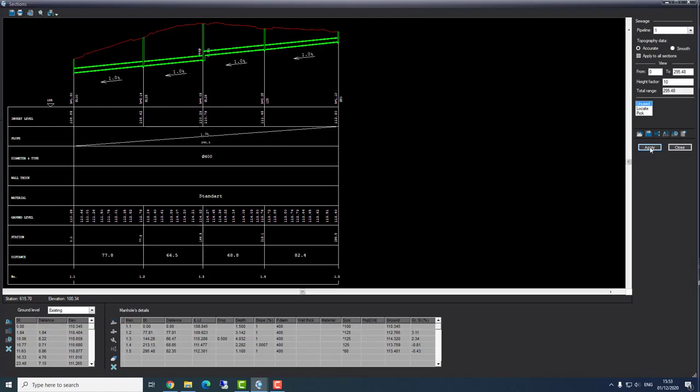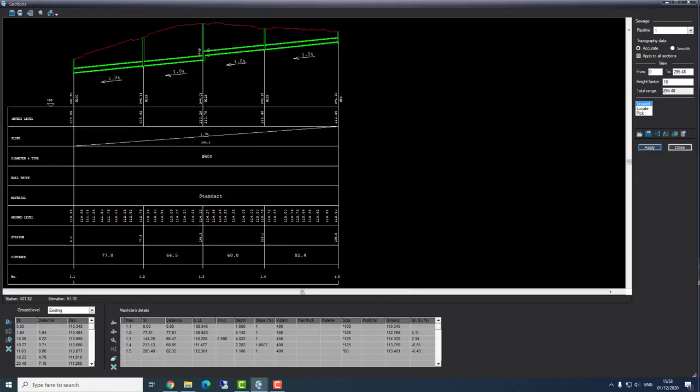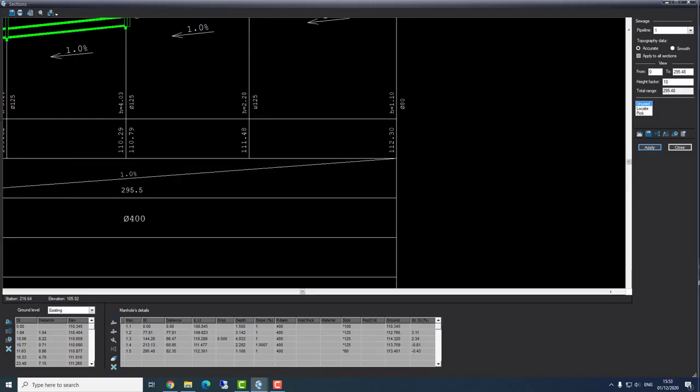And now we can see the diameter on the drawing itself, right here. Oh, see right here I don't have the diameter mark. This is because I forgot the little star right here. So I will enter it, 125. I'll press apply. And now I have the mark of the diameter, 125.